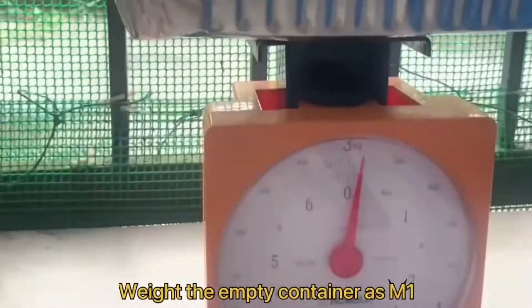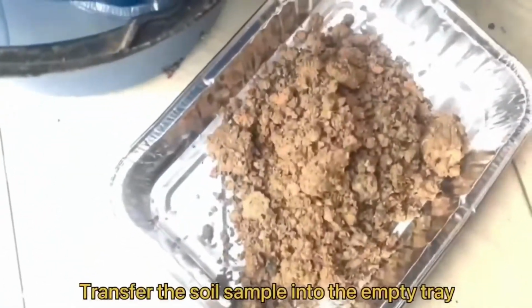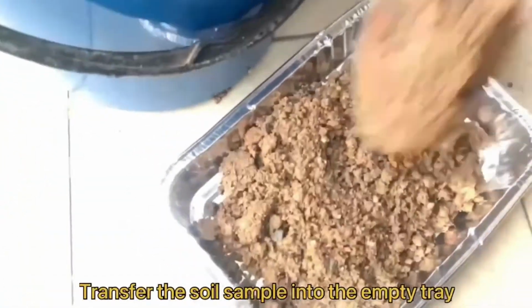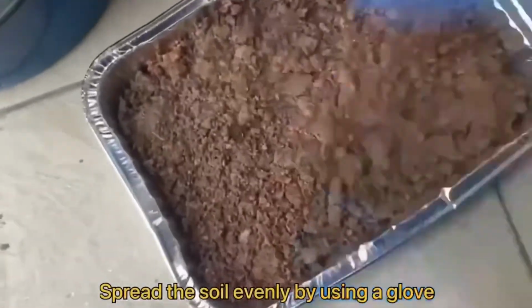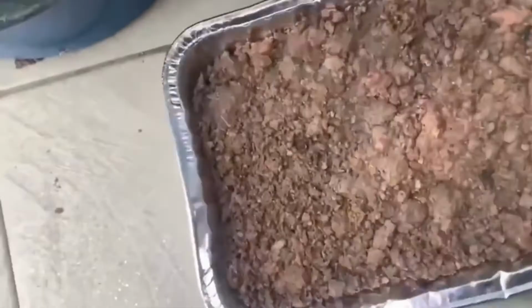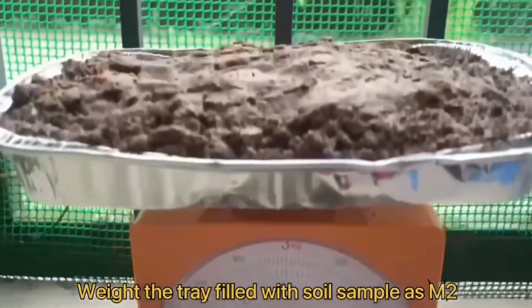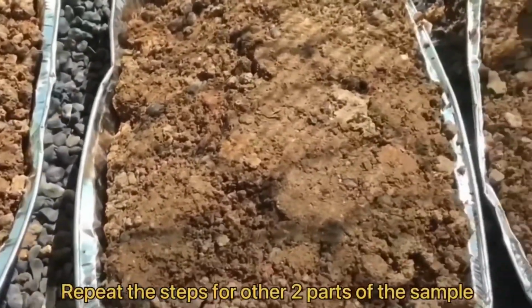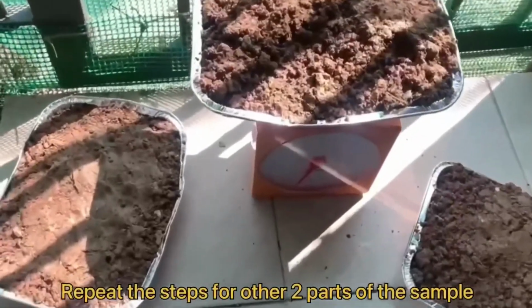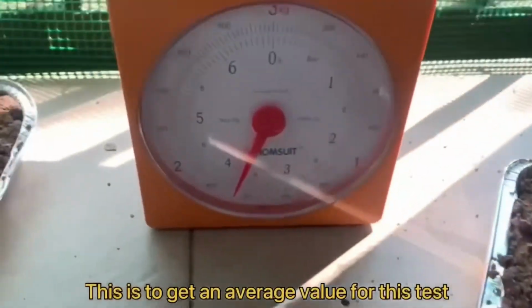Weigh the empty container as M1. Transfer the soil sample into the empty tray. Spread the soil evenly by using a glove. Weigh the tray filled with soil sample as M2. Repeat this step for the other two parts of the sample. This is to get the average value for this test.